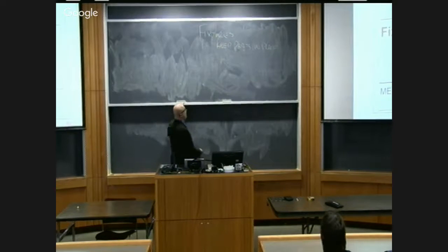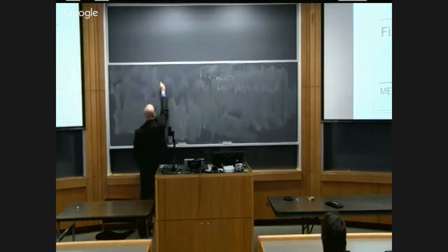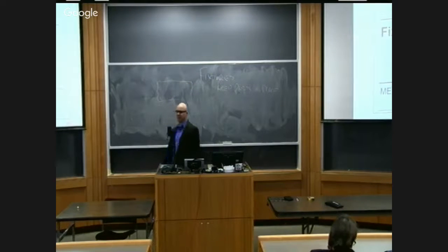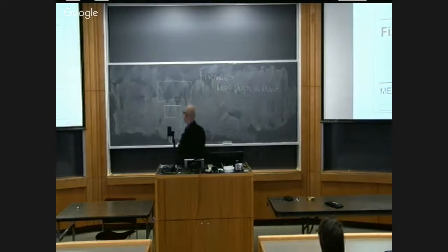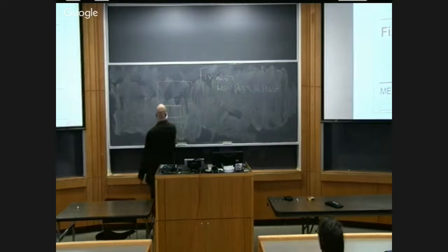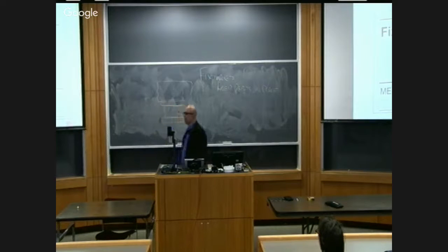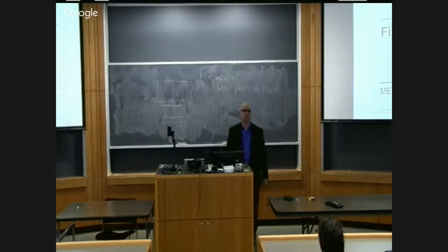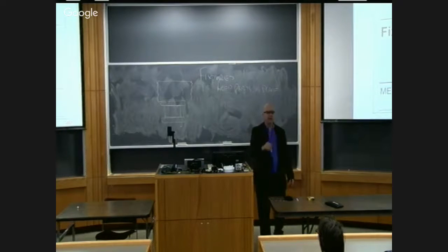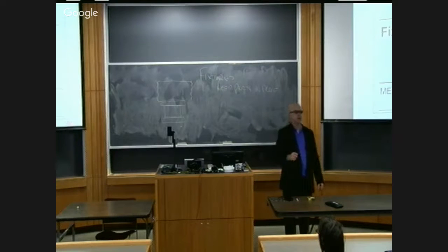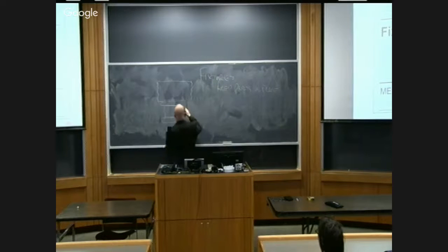If I, for example, had a piece of stock material that looked like this, those wavy lines indicate that I cut it with a bandsaw. This is a very wavy bandsaw cut. And I want it to look like this. Let's say I'm intending to hold it in a vise, and my vise jaws are typically that big. So what would the process of cutting that have to be? If I want to clean up the wavy edges on my part, how could I do that? We should use an end mill, not a drill. We're going to move sideways. Okay. So what I could do is fixture it.